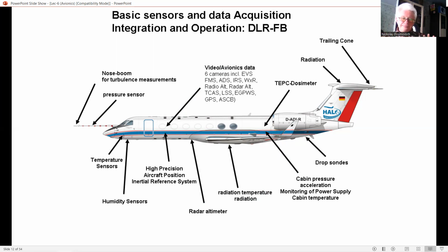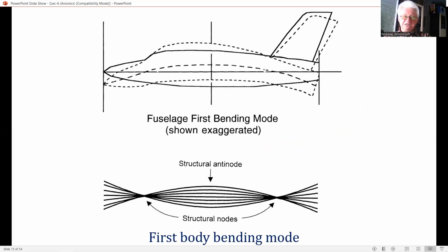Sufficient to say that optimal handling requires a blend of control terms, the mixing of which needs to be adjusted over the flight envelope. Air data gain scheduling is necessary to adjust the gearings of the control terms to cope with the changes in control effectiveness over the flight envelope, as explained a bit earlier.